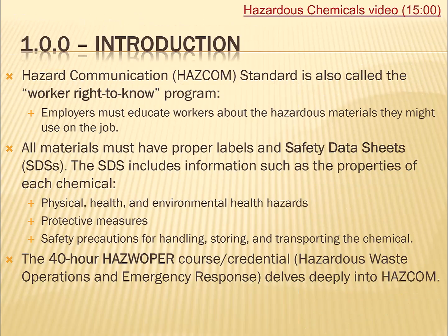So, the hazardous communication, or HAZCOM standard, again called the Worker Right to Know program: employers have an obligation, a responsibility to educate workers about the hazardous materials that they can end up using on the job. All materials must have a proper label. Every material must have a proper label on it, and you must have a safety data sheet on file.